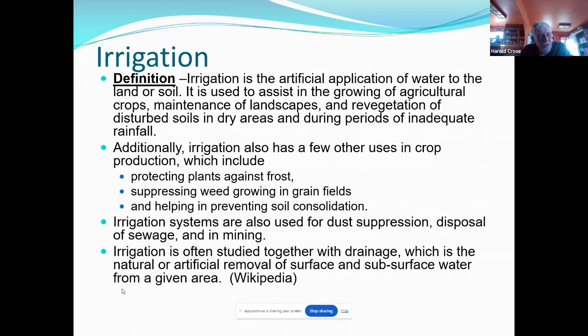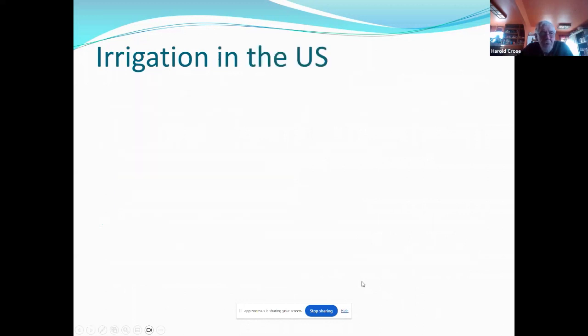And we've also used drainage as a backup for subsurface moisture, where we've put structures at the end of drainage systems where we can shut the drain off and have the water backed up through the drainage system to supplement the irrigation systems during the driest parts of the year. So there's things we can do with water, but the primary thing is understanding what those water levels are and what the water table is for your situation.